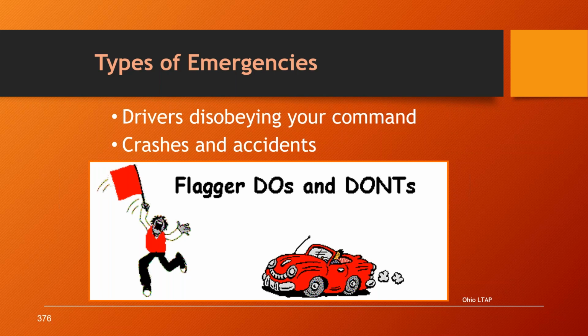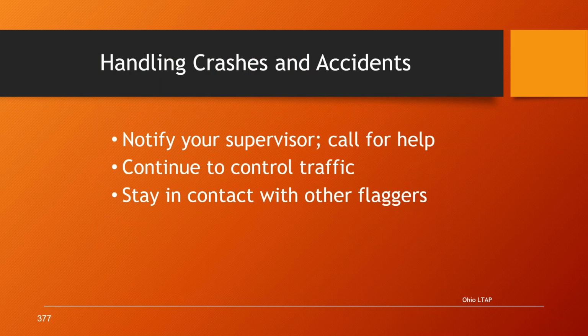When I say emergencies, I'm talking about maybe a driver is disobeying your command to stop, and maybe they've caused a crash. So we have to be able to protect ourselves and then also handle the crash. We need to respond and communicate that to the right people. So if a crash happens, you want to notify your supervisor and call for help as soon as possible. But we also need to continue to communicate to the motorists out there as well. So we need to also continue to control traffic and stay in contact with the other flaggers.